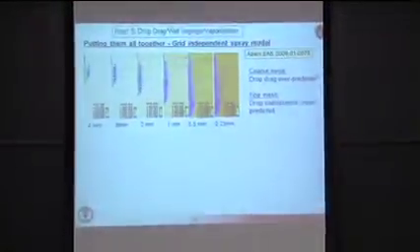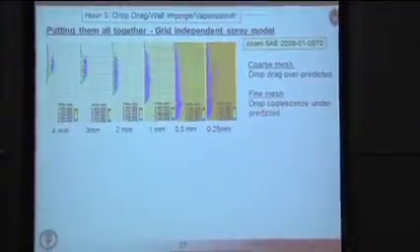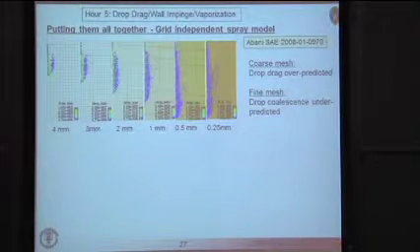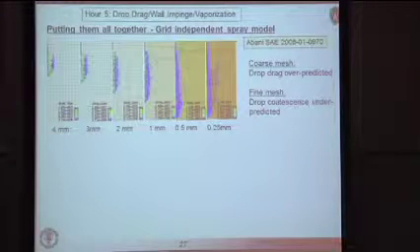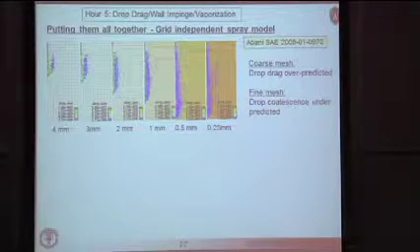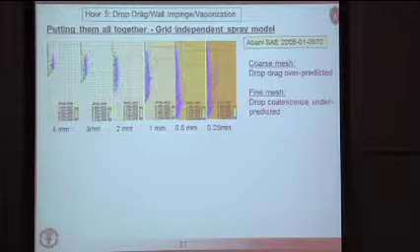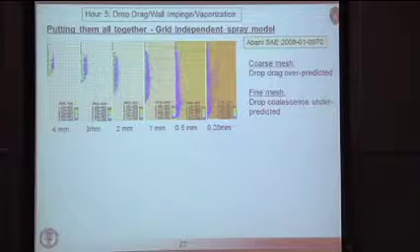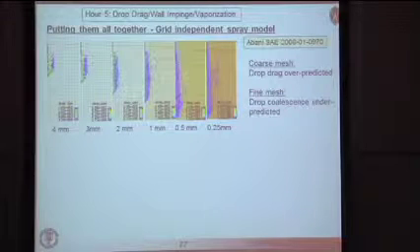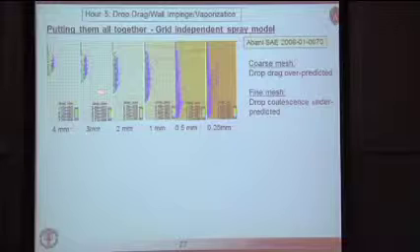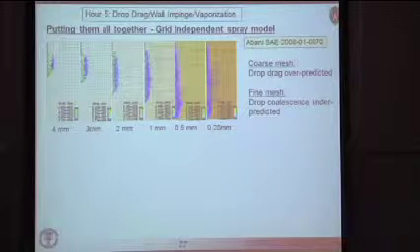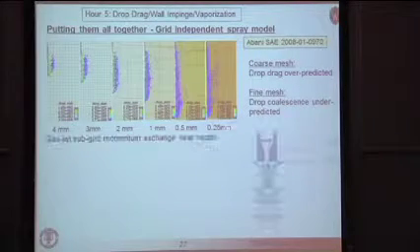The other thing is that I mentioned, somebody asked about droplet collision and coalescence. If you have a fine mesh, like this one over here, it's possible you only have 1 or 2 droplets in a cell, and therefore there's no collision process that takes place, compared to the case here, where you have many droplets in the cell, lots of collisions and coalescence. So both of these effects are the explanation behind why this is so grid dependent.